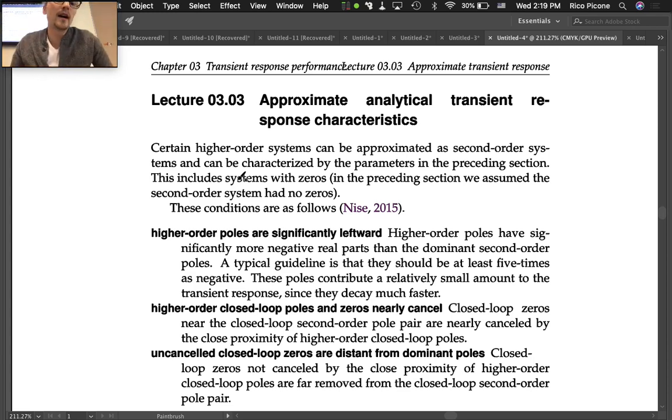And we defined them just in terms of lengths of time to get to a certain feature in the response, or intervals of time for a feature to emerge, and then also relative height in the percent overshoot case, or a relative quantity of the response, so relative to the steady state value. So those were the 4 that we defined.